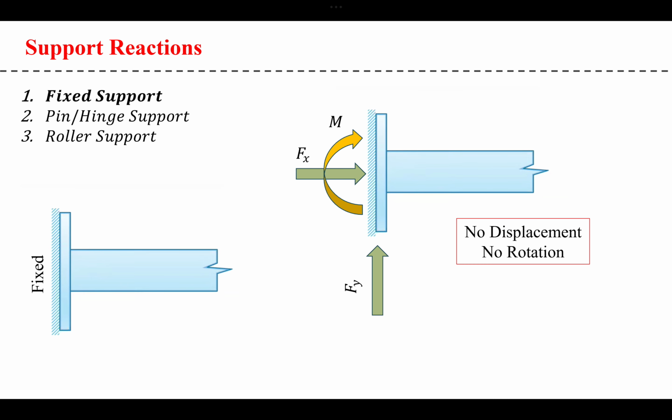So as a fixed support, there will be no displacement. It will be stopped by your Fx and Fy, the reaction force that is parallel to the surface, Fy, and the reaction force that is perpendicular to the surface, Fx. So there will be no displacement. Additionally, there will be no rotation in the fixed support because it will be resisted by your induced reaction moment.